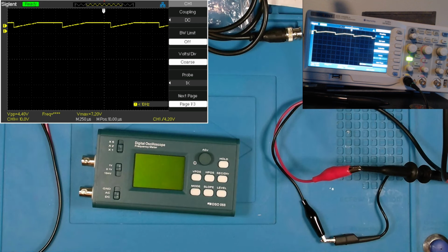Now, if you were to use a multimeter, you'd say, well, my DC reference voltage is 5 volts, but I'm measuring 7. It's a bit high, but maybe you're still measuring 5, or slightly above or below 5 and thinking it's good. But unless you actually see that voltage over time, how would you know if it's dirty or not?